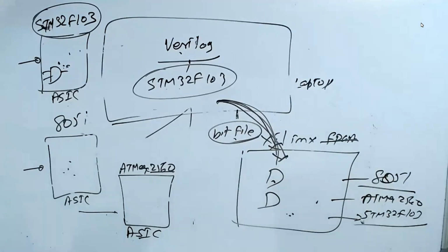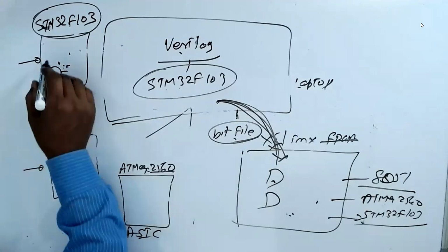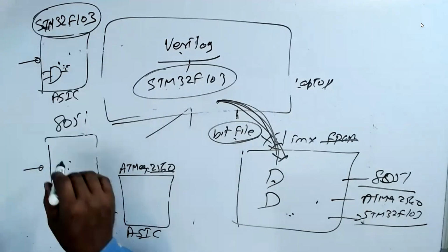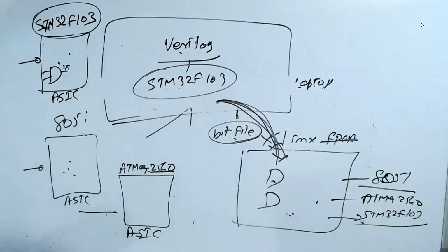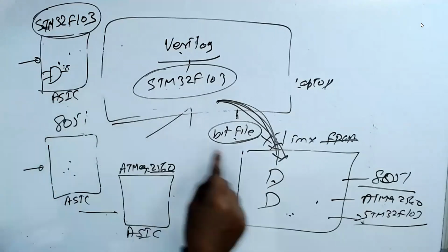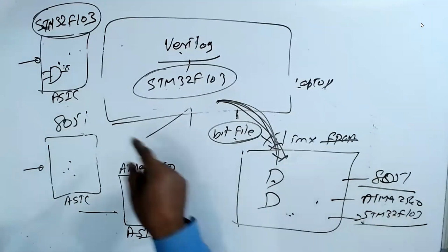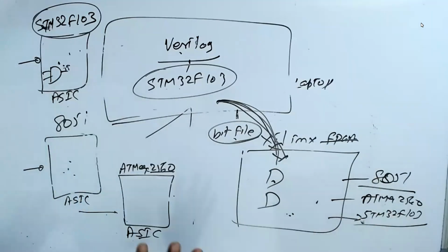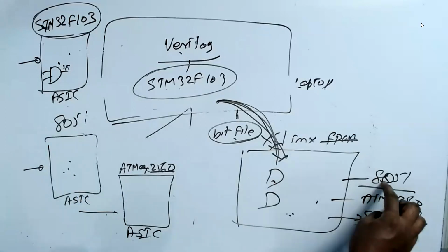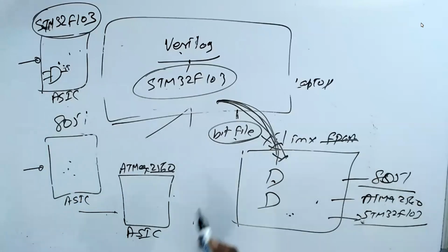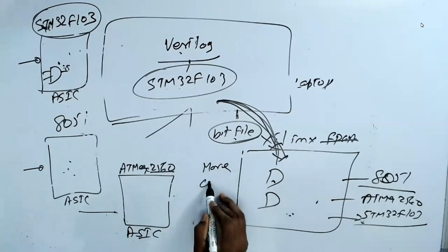Now you understand. Yes, sir, got it, sir. Clear, thank you. But then, when the FPGA can be any IC, why do I have to buy the others? FPGA is very inefficient. There will be lots and lots of gates, and you use only a few for the 8051. So the FPGA will take more power and be costly.